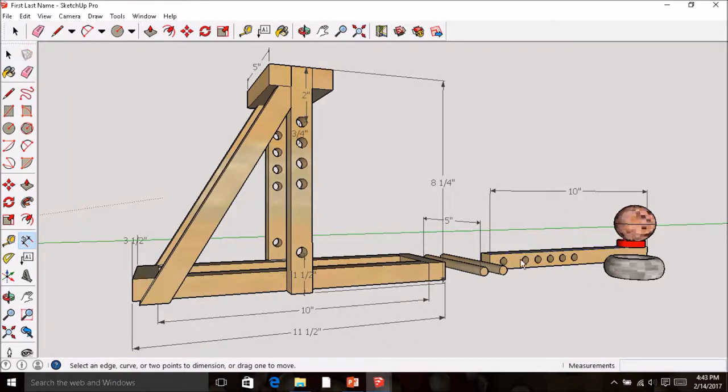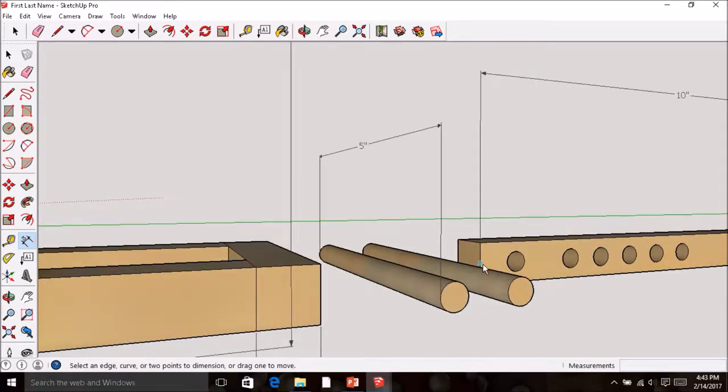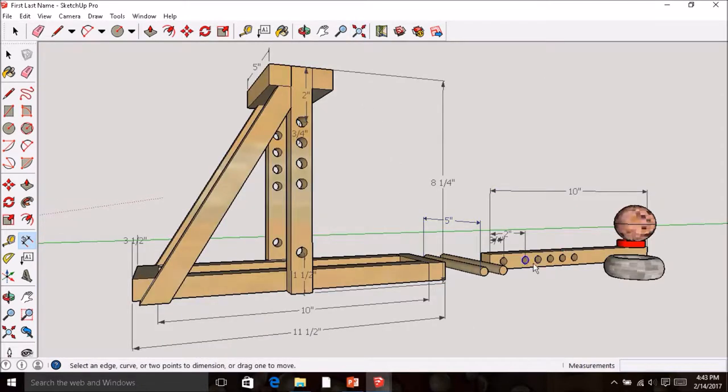We're going to come over and dimension these last circles that we did over here, and then our drawing will be ready to print. So I come out to center, know that that's 3/4. Make sure it says center. That one should be 2 inches. And we can hit zoom extents because we know those other ones were 3/4 of an inch off.